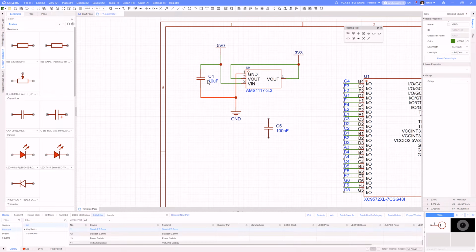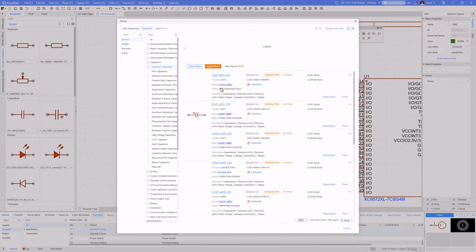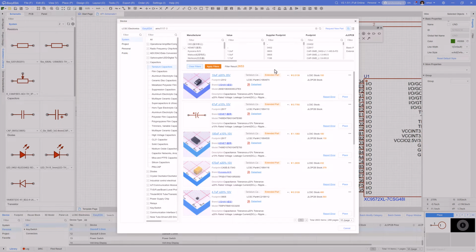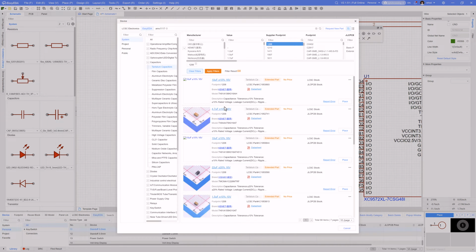And if that's not the size you want, again, you can go in here and maybe you want to find different size capacitors. So maybe I'm going to do a tantalum and I want to find a 1206 type of size. So I could say, well, let's go find a footprint that's a 1206 and apply that. The actual value of this isn't so important.